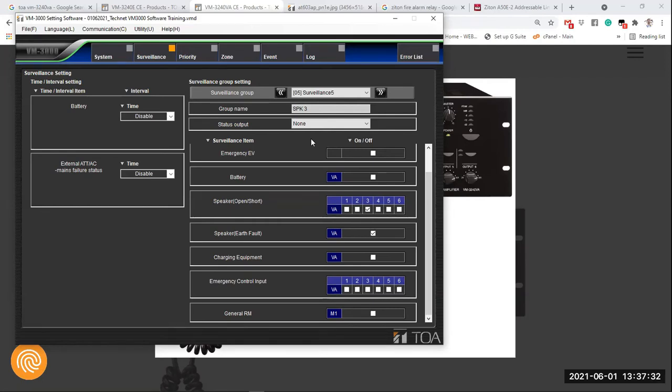So you will need to bring your laptop to site and download the file and work with your laptop to pick up what exactly is the fault. So it is nice to create different fault groups, different faulty patterns, so that the system can tell you, I am displaying this fault because I am seeing an open circuit or a short circuit on speaker line number 3, and you can deal with that speaker line. You don't have to worry about a lot of things.